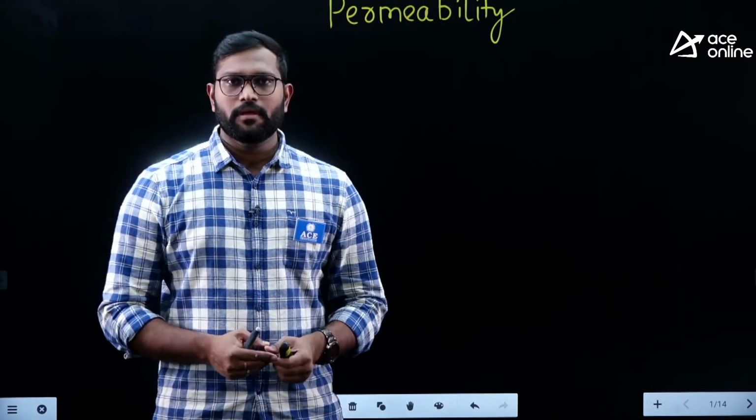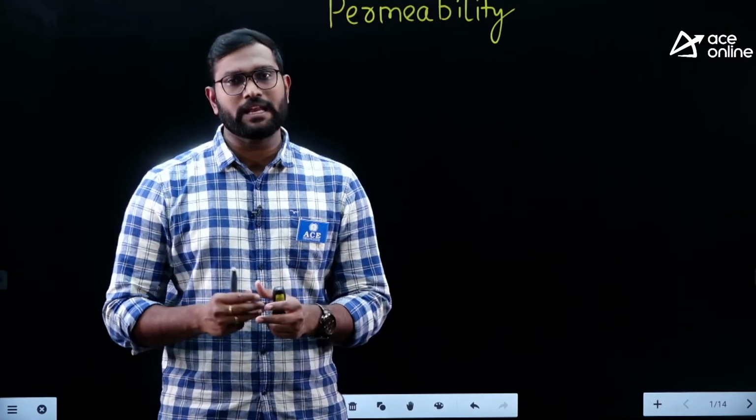In simple words, soils with a large void space definitely consist of large particle sizes. Gravel has more permeability than clays. In clays, the number of voids is obviously more, but each void space is small. Similarly, it can be the same soil with a different structure. So different soils have different permeability. But in the same soil, is the permeability a constant? No. It is based on the denseness and on the structural arrangement.